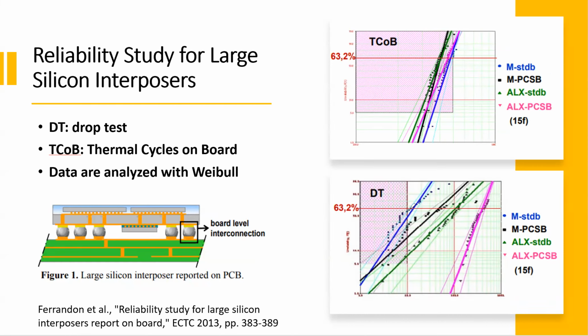Nothing is perfect in this world. And then you have to present this data in a Weibull distribution. And once you've done that, you will know whether your product at the end of the day can meet the spec or not. So you go through this simple process. You follow the instructions according to the same spec, and then you do your test, and you present the data with a Weibull. And then you will quickly figure out whether you pass or not. That's from the manufacturing perspective.